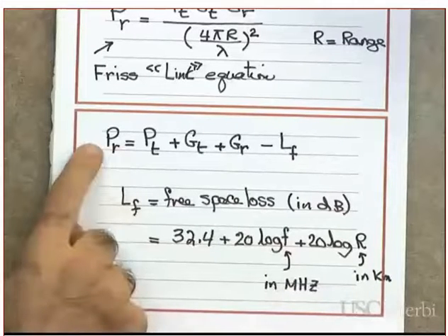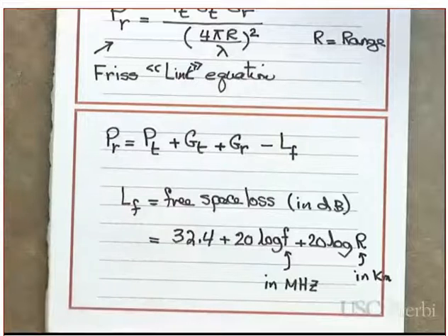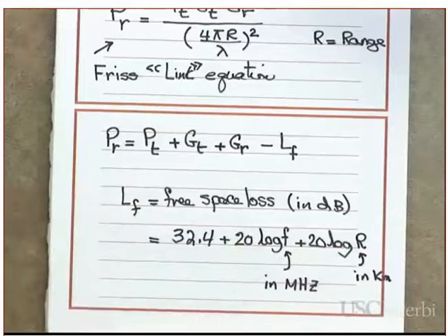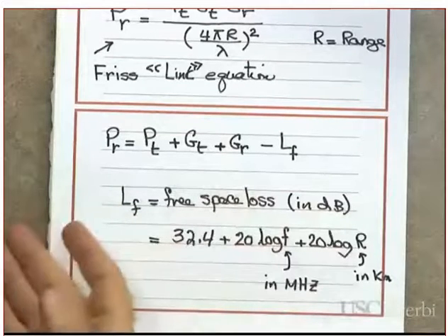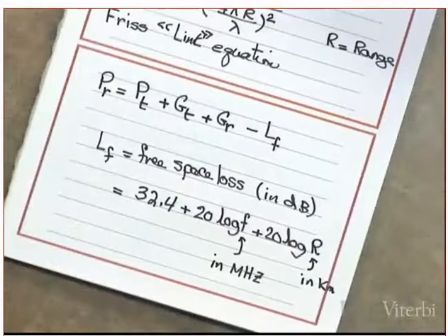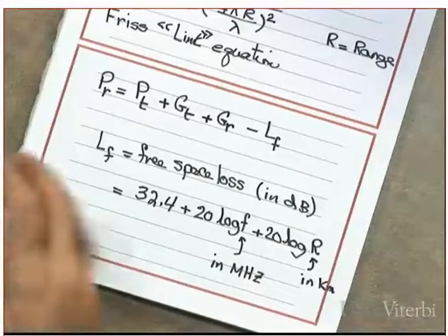So in reality, by the way, how about fading or shadowing? Do you need to put it in the link budget? You need to take it into the link budget. Are you following me or not? Shadow fade, the shadow margin or fade margin. You need to include it in your link budget. You cannot just put the free space loss and say, well, hey, that looks good. Did you get my point or not? Yes or no? Okay, so good.